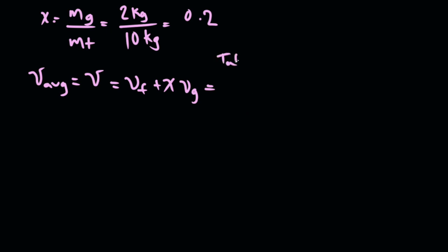Through a table lookup, we know what V sub F and V sub G are. Actually, this is V sub FG, sorry about that. We can calculate V sub FG because it's a subtraction. So now we know V sub F was equal to 1038.